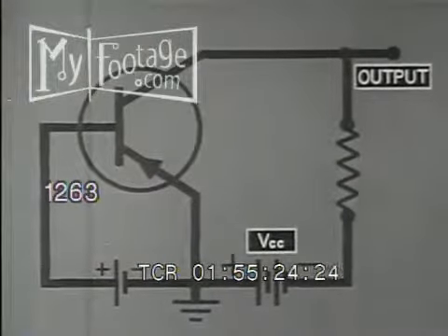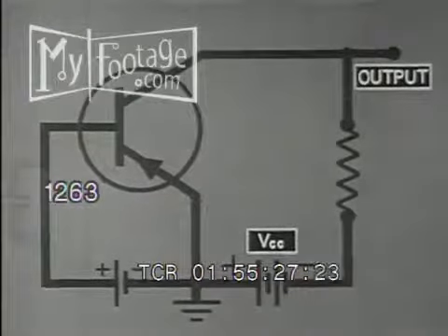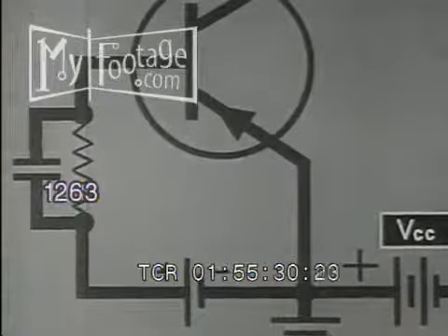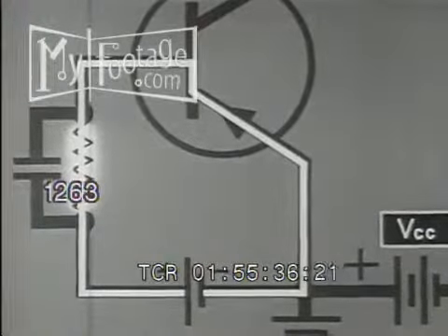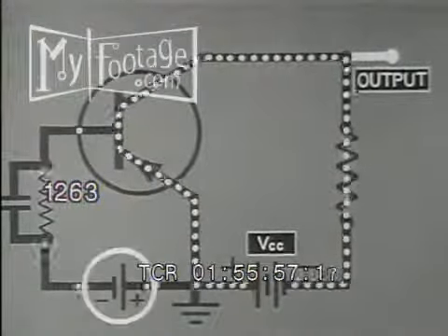To make the switch respond more quickly, the circuit is often arranged like this. The input resistor limits the emitter current so that just enough carriers enter the base to keep the collector saturated, with very few left over to become stored minority carriers in the base. When the switch is turned off, there are few stored holes to maintain the collector current, so it stops very quickly.